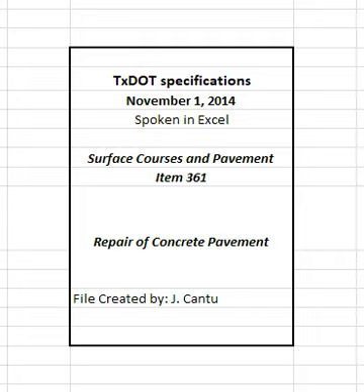Repair areas may be adjusted after removing distressed concrete. Switch the half-depth repair to the full repair if exposed existing longitudinal bars are deficient, as approved. Compensation will be made for unexpected volumes of repair areas or changes in scope of work. 4.1 Half-depth repair. Repair locations will be as indicated on the plans or as directed.